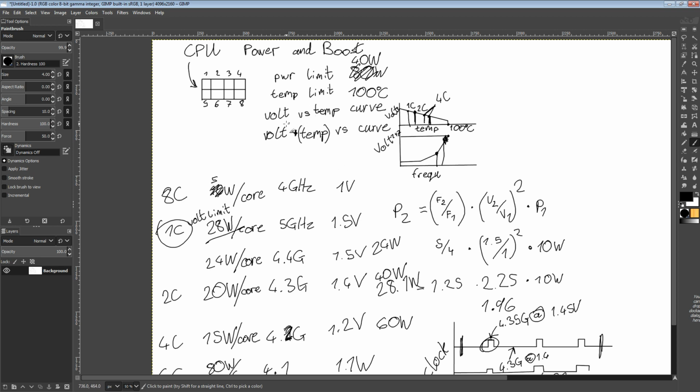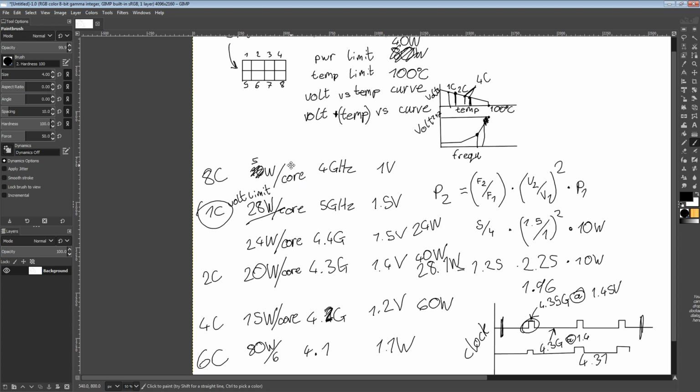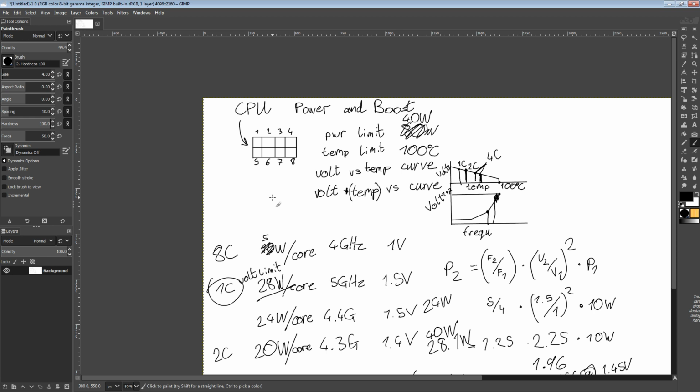Whereas AMD's chips can't clock that high, so AMD's solution is a boost algorithm that is ridiculously aggressive, opportunistically going, hey, we have just enough power limit and just enough temperature limit to boost the frequency by another 25 megahertz if we raise the voltage by another 50 millivolts, and it's going to do it, right? It's like, I'm not violating any limits. Go for it. The side effect of that is potentially very high single core temperatures,